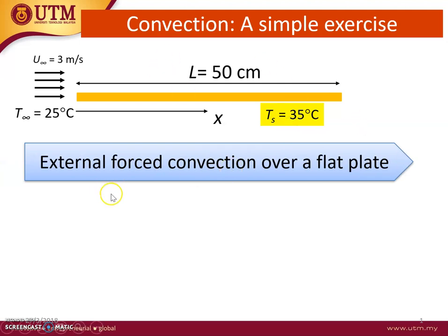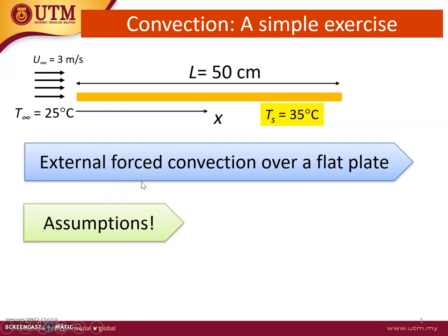Now, this is definitely external force convection analysis, flow over a flat plate. First, we have to make our assumptions before we move on. The first being steady state, because if the flow of air over the flat plate is not steady, then you may not just use the Newton's law of cooling simply. The h would have varied with time.